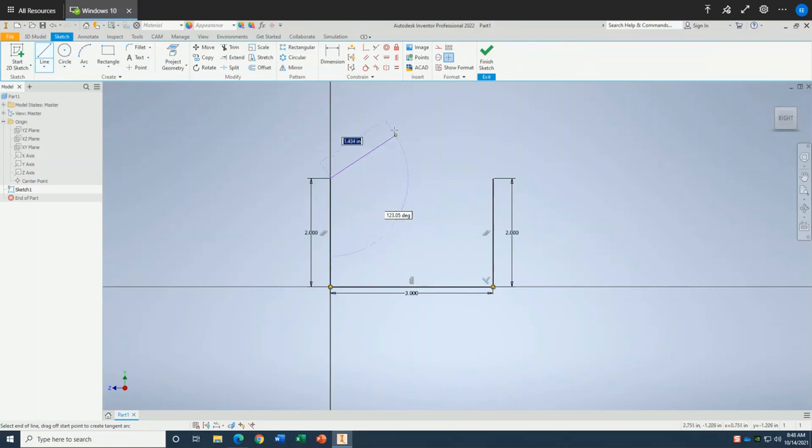At this point, now I need to draw the ridge of the house. This has to line up with the midpoint of the house, so that's why I'm moving my cursor to the midpoint of the 3-inch long line to see the green line. That midpoint indicator is showing me as a dotted line.